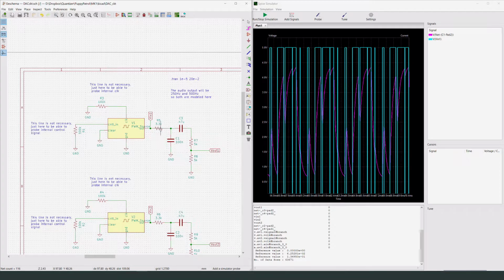And so we selected these values so that it will not saturate or charge too quickly or too slowly to actually get an output. And another thing to keep in mind is that this is a low pass filter. So it will pass lower frequency signals and block or attenuate higher frequency signals. And so it's important to get your calculation so that it's in between, getting a smoother charge cycle, right? And not filtering out your frequency of interest.